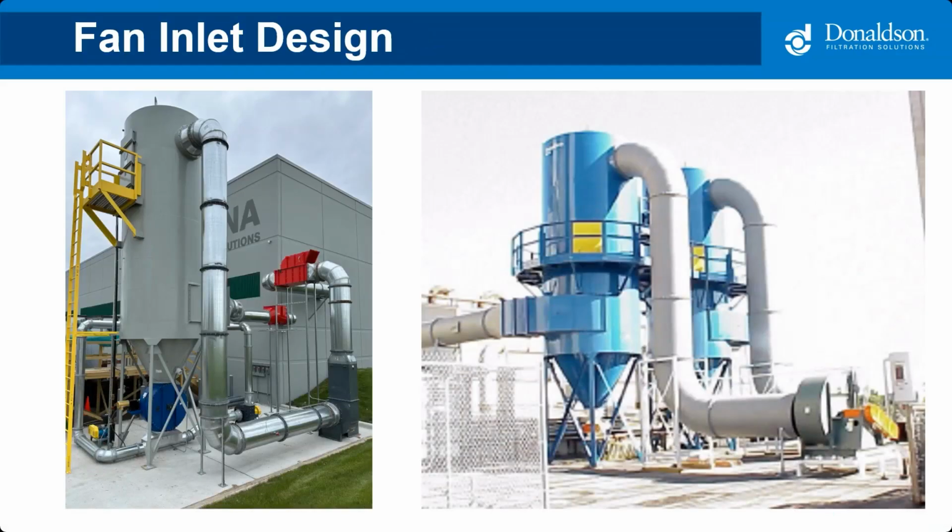Well, another thing we need to consider in fan systems are the inlet and outlet configurations. On the inlet side of the fan, we need to look at keeping the airflow as linear as possible so that fan wheel can take as big a bite out of the incoming airstream as possible. The example on the left there has a nice long run of straight duct right into the inlet of the fan. This is what we want to see.